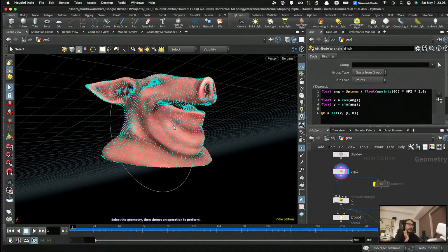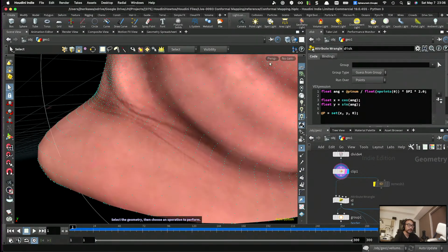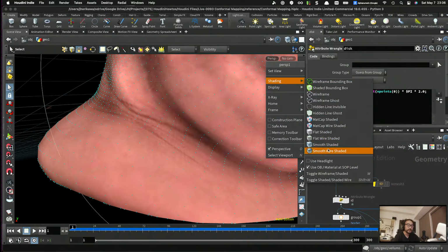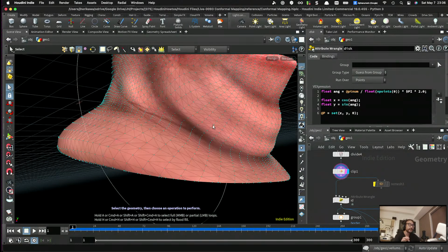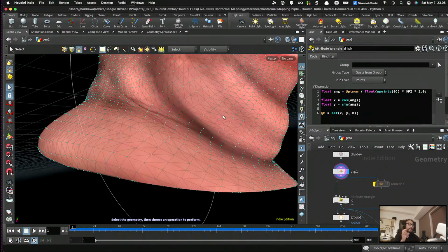Now there is one single constraint that I'm going to attach to the edges of this geometry, which is a spring or string constraint onto every single edge with a rest length scale equal to 0, meaning it's trying to become a single point.